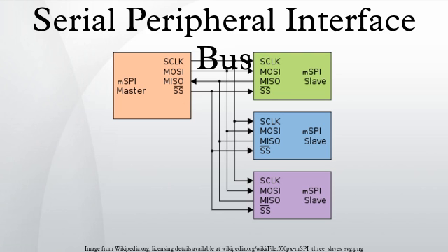Example of bit banging the SPI master protocol. Below is an example of bit banging the SPI protocol as an SPI master with CPOL equals 0, CPHA equals 0, and 8 bits per transfer. The example is written in the C programming language. Because this is CPOL equals 0, the clock must be pulled low before the chip select is activated.